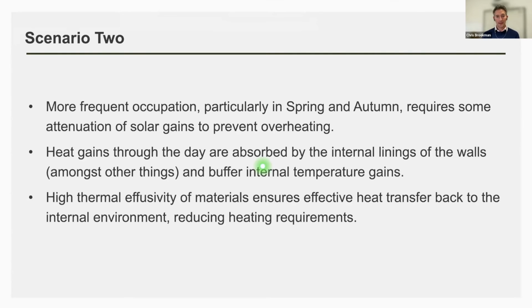If those heat gains are soaked up during the day, you come back to a nice, warm, comfortable building. Those heat gains are slowly radiated back towards the interior, and that pushes the time at which you might start putting your heating on much further back. And again, having materials with high effusivity, a higher ability to transfer that heat back, also means that you're radiating more of the heat rather than not.